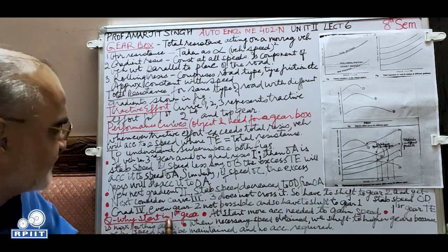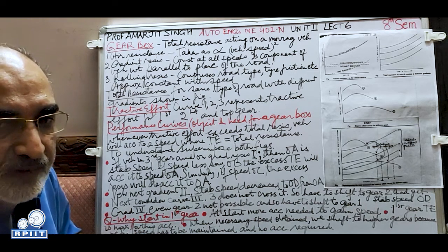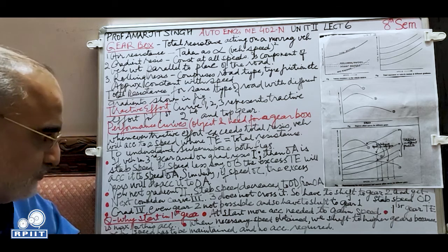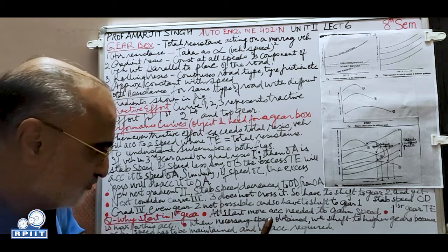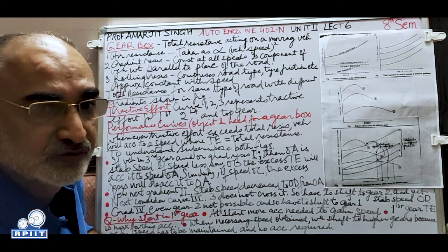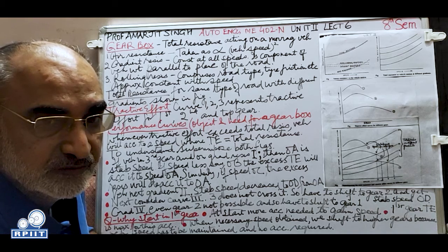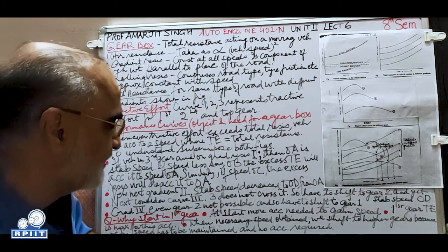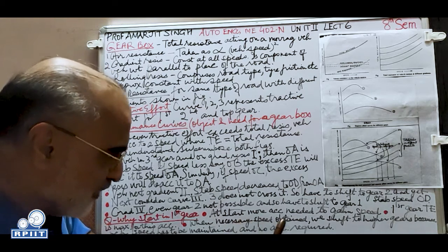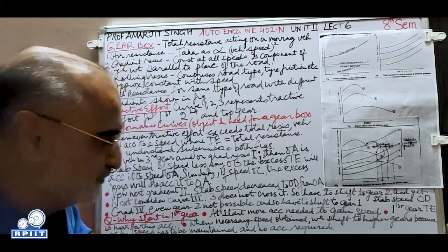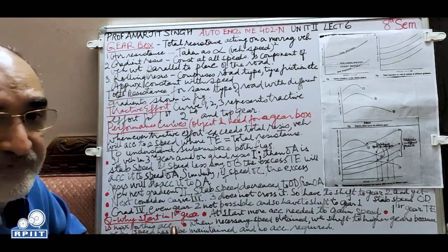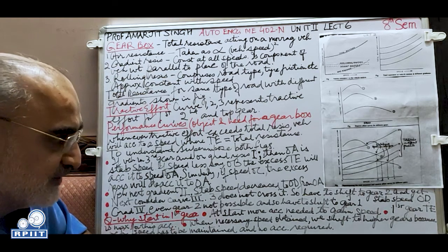Now let's come to the question, why start in first gear? Why do we start a scooter or car in first gear? At start, more acceleration needed, more tractive effort. Just imagine a car which is weighing more than half a ton. To start it, we need very large tractive effort. So at start, more acceleration is needed to gain speed. The first gear tractive effort is maximum for this acceleration, which I have just said.